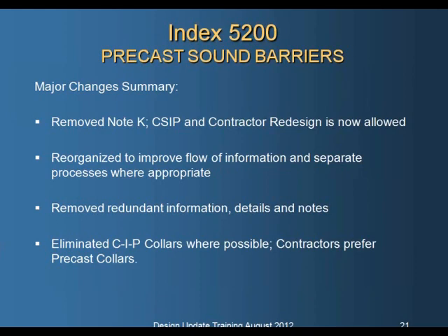So we reorganized it. We've also removed redundant information, details and notes, and we've eliminated cast in place collars where possible. The contractor prefers the precast collars. We only used the cast in place collars where the precast collars would not work properly.